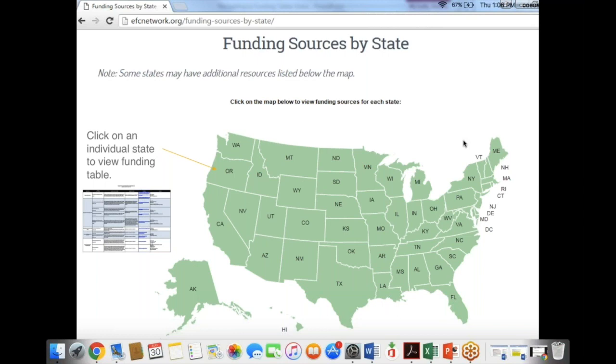So we went with the operator to talk through some of these useful life estimates, and like, okay, you put this thing was 5 years past useful life, but you're still using it. It seems in pretty good shape. What do you think? Oh yeah, I can use this for 10 more years. It's no problem. So you find out that when you actually talk about each individual piece of equipment and do a different assessment that is not age-based, but more condition-based, maintenance record-based. So have I been doing the maintenance? Do I have spare parts available?